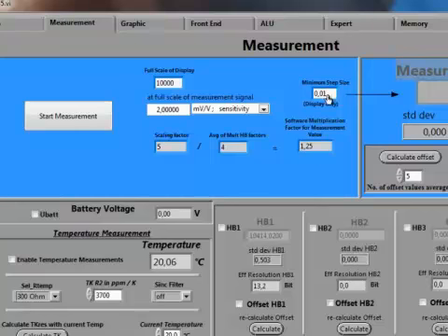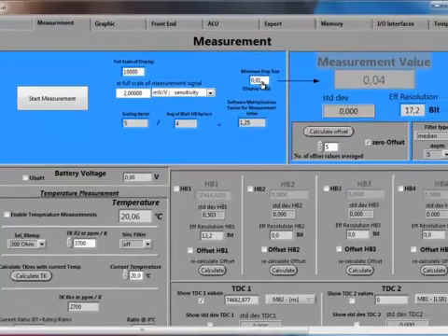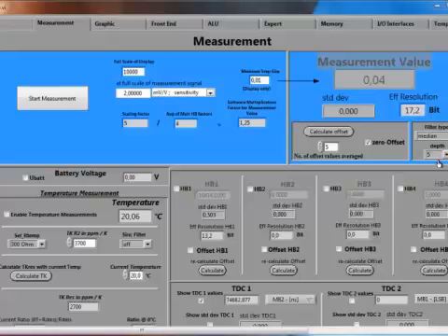You can set the minimum step size for measurement here. Please note that all the settings done in this area are purely only for the evaluation software. They have no effects on the chip's configuration itself. With these settings, the result read from the PS09 chip can be interpreted more easily.